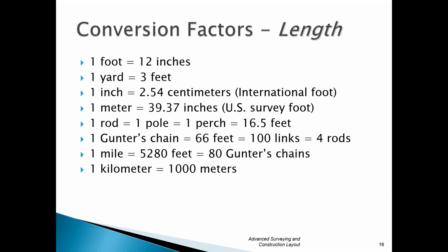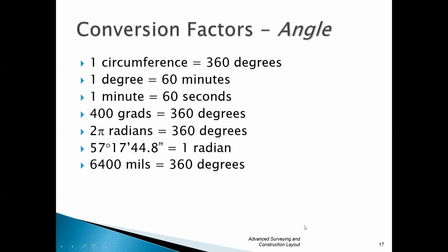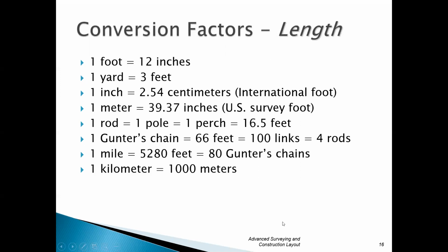So depending on what state you're in, you're either using this equivalency or, whoops, let's go back. You're either using the international or the U.S. survey foot. So just to give you an example, most of the states are U.S. survey feet states, but a couple of them aren't. Ohio is a U.S. survey foot. Indiana and Kentucky, I believe they're all U.S. survey foot, but Michigan is not.